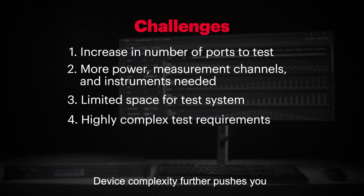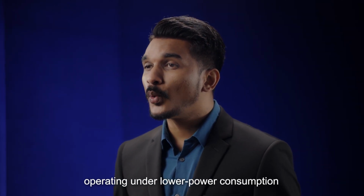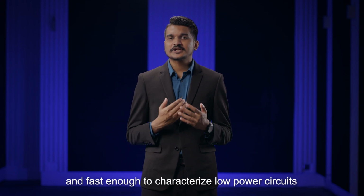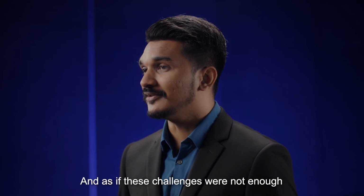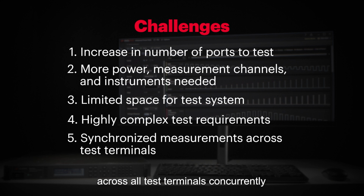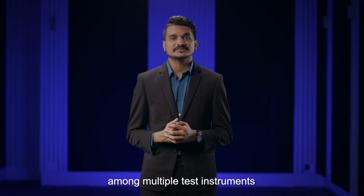Device complexity further pushes you to test at a higher accuracy and speed due to the static and dynamic characteristics of low power ICs operating under lower power consumption. Basic test instruments are simply not precise and fast enough to characterize low power circuits that operate among multiple states such as sleep and active. And as if these challenges were not enough, you need to perform and synchronize measurements across all test terminals concurrently while preventing device damage during testing. This demands sophisticated test automation software and complex synchronization among multiple test instruments.